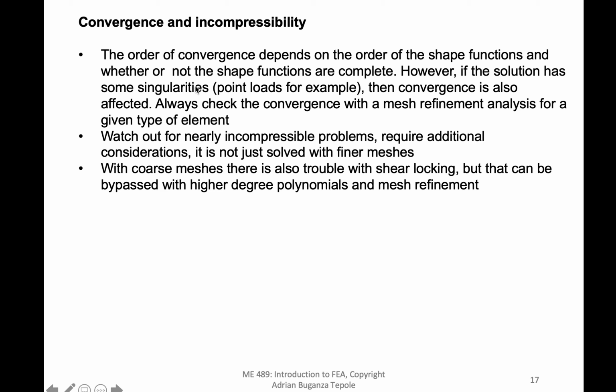And then I guess this one was the first point, but I am covering it last, which is the order of convergence. I think we did it for both heat transfer and 1D elasticity. In one dimension, when I asked you to solve the problem with linear elements or with quadratic elements, what you saw is that the solution converged quadratically for the displacements or temperatures and linearly for the gradients with the linear shape functions.